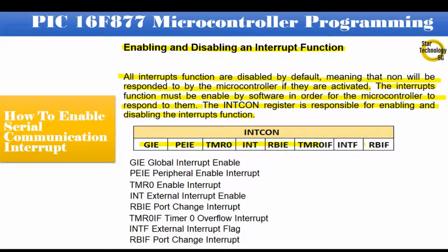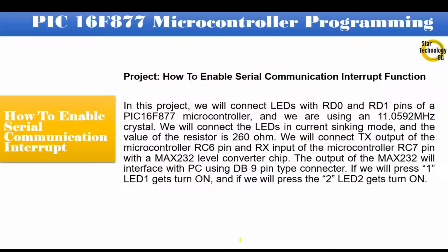Here is the INTCON register. GIE, Global Interrupt Enable. PIE, Peripheral Interrupt Enable. TMR0IE, Timer 0 Interrupt Enable Bit. INTE, External Interrupt Enable. RBIE, Port Change Interrupt Enable Bit. TMR0IF, Timer 0 Overflow Interrupt Flag. INTF, External Interrupt Flag. RBIF, Port Change Interrupt Flag.